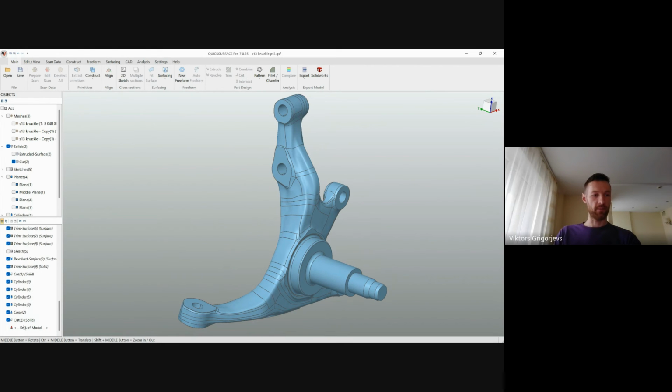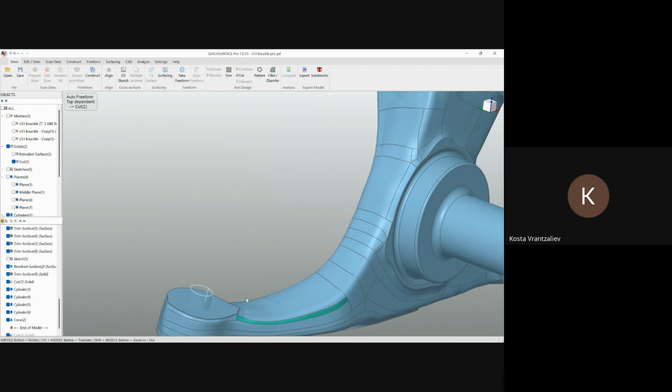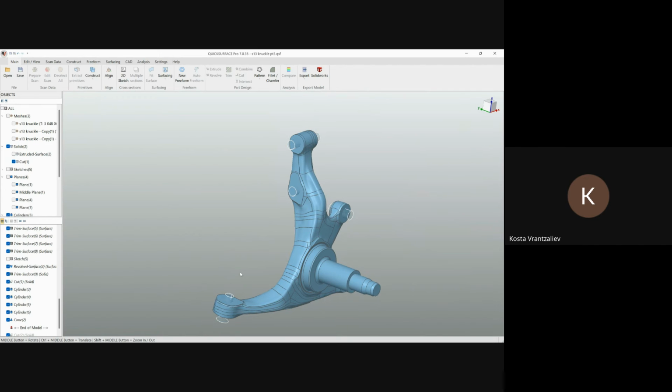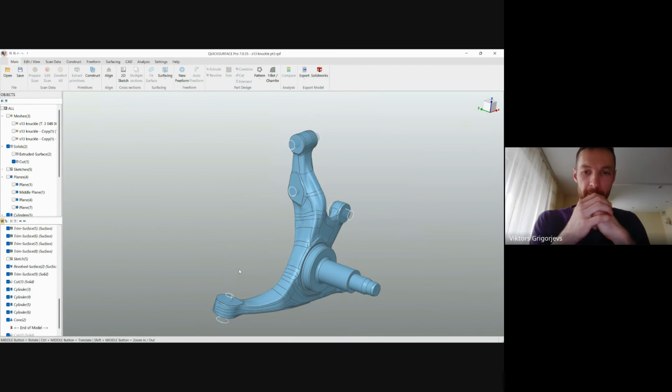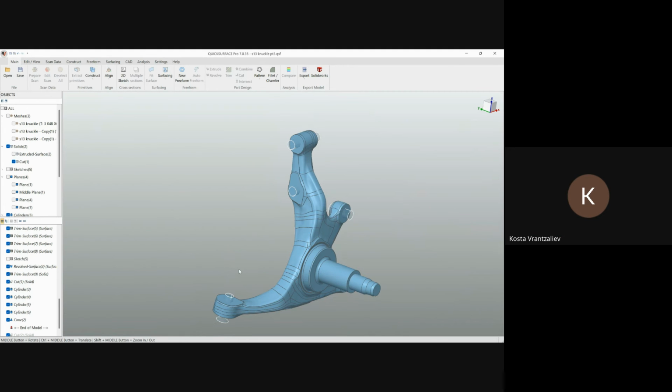And actually, okay, let's do it a different way. This is a very good question about the cut from solid body or trim. Now, in general, all the cut kernels are much more like Boolean operations. This means that whenever it's possible, I recommend that you use Boolean cut or Boolean join. You can always use trim.